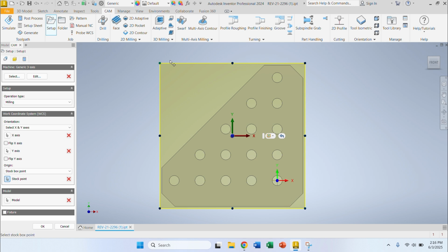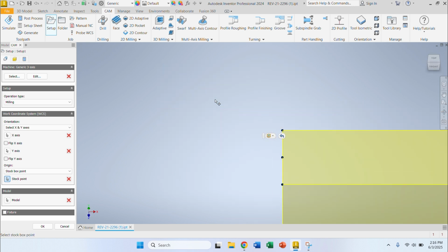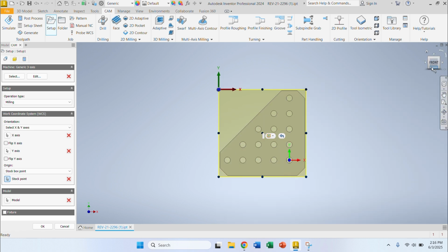However, that's actually wrong. What you want to do is you want to get a more 3D view. And if you zoom in, there's actually 3 points here. I always go with the top of the top left. It's good to keep it always one single point so you don't jumble it up. So there's our origin set. So this will be our 0, 0, 0 actually. It's 3 digits because it's X, Y, and Z.